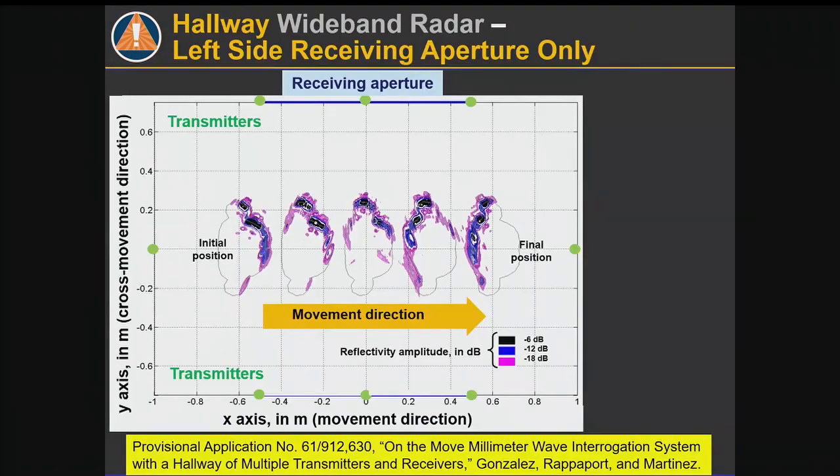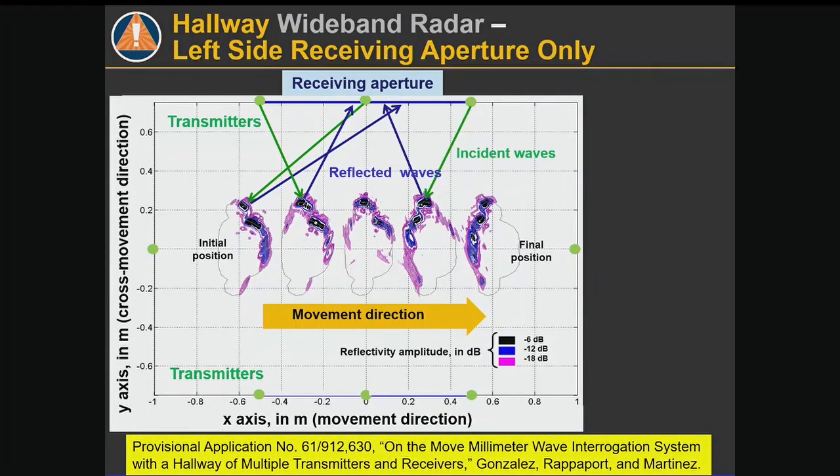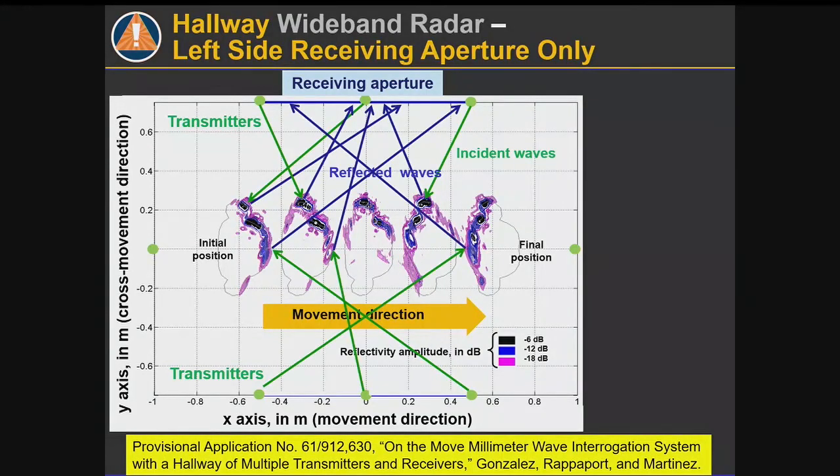That's the innovation. So, for example, we have a transmitter bouncing off a person's arm, picked up by a receiver in the aperture. That's fine. How about this one? That's also picked up, with multiple positions. These aren't chronological. The person is moving from left side to right side across here. Another case picks up that one. But now, if we want to image the person's front, we have a transmitter on the opposite side, and where's it going to reflect to? A receiver on the original side. And similarly, this one here bounces off there, and this one over here gets the back. And so you can see that you need multiple transmitters.